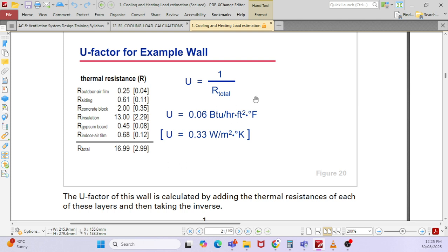That is why whenever you see the architectural schedule for the U value, you will find external wall 0.39, but for internal wall, you will find 2.2.